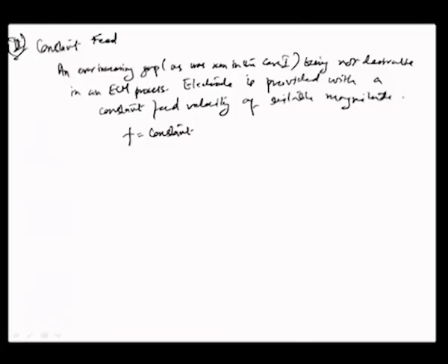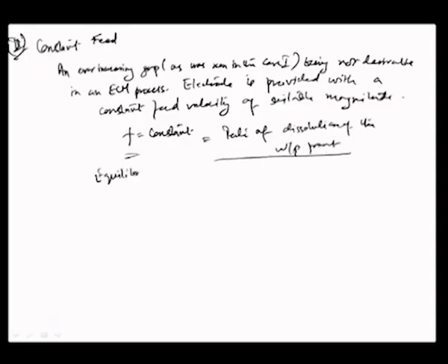So, what eventually would happen is that there would be a case where the feed actually becomes equal to the rate of dissolution of the workpiece front. In other words, there is an equilibrating condition which would arise.